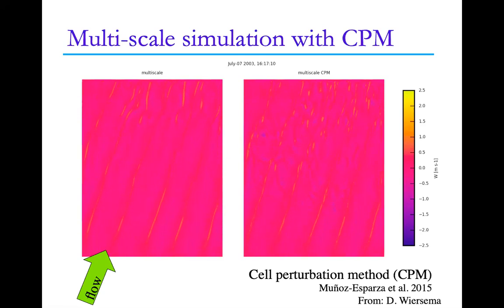But that's one of the things that's hard with a standard setup in WRF. As you go to finer resolution, there isn't fine scale topography beyond 1 kilometer resolution that's allowed in WRF. So it's something you have to do manually if you want to include the smaller scale features. But then if you include the smaller scale features in topography, sometimes you run into stability issues because of the terrain following coordinates. So it depends how fine you're going. Yeah. But the idea is just to trigger the very smallest scales.